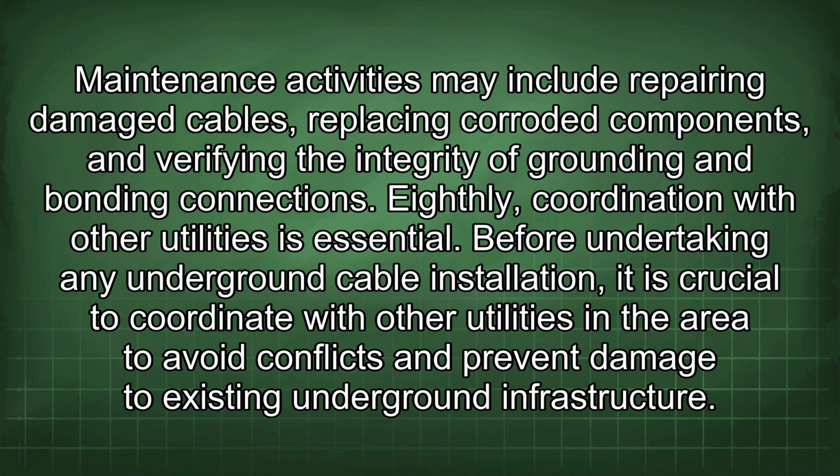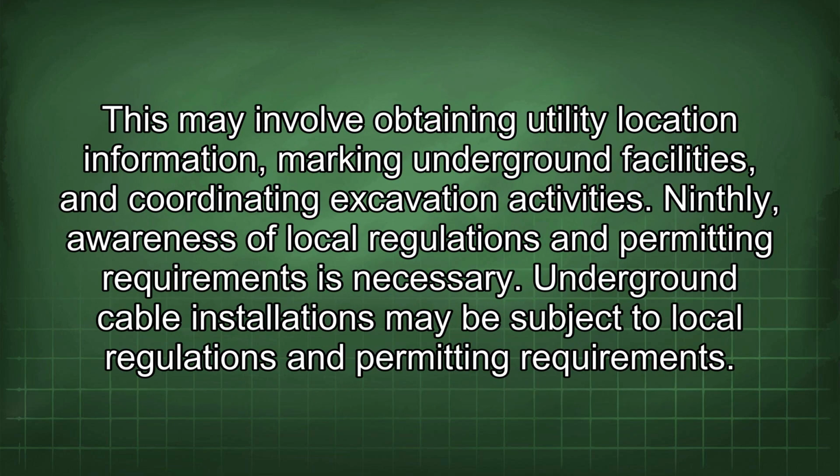Eighthly, coordination with other utilities is essential. Before undertaking any underground cable installation, it is crucial to coordinate with other utilities in the area to avoid conflicts and prevent damage to existing underground infrastructure. This may involve obtaining utility location information, marking underground facilities, and coordinating excavation activities.